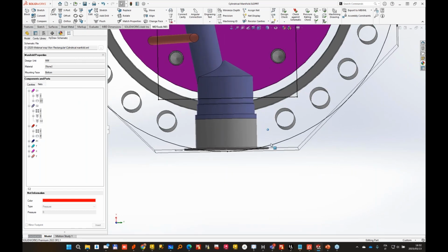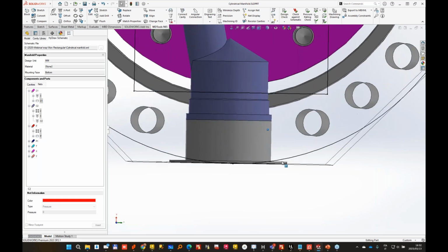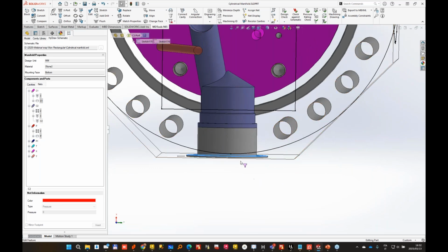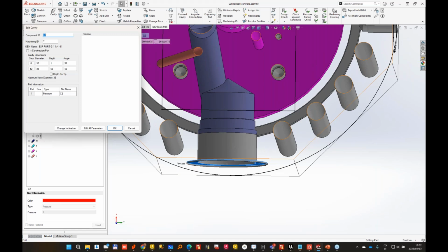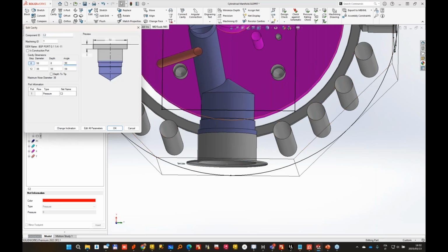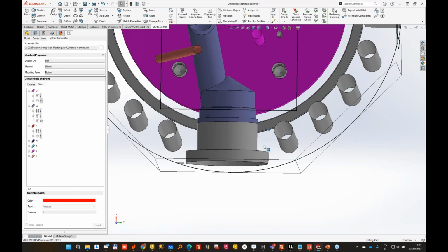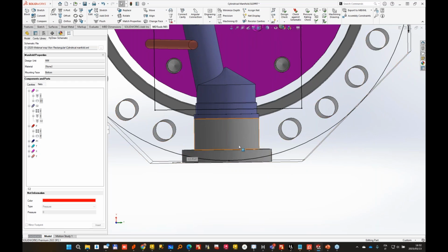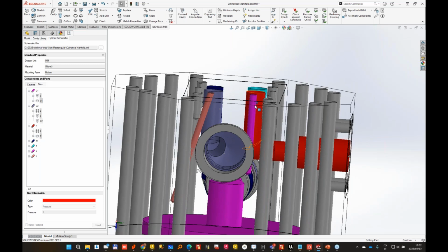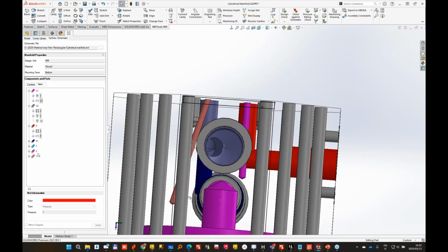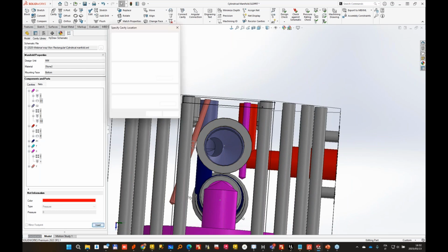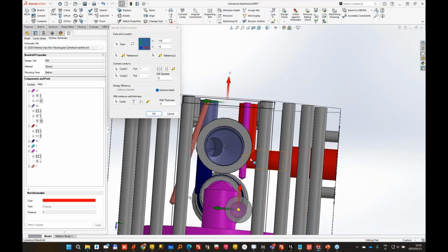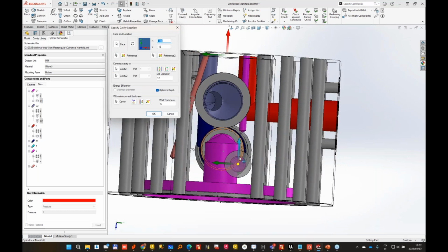Since, for the same statement I made earlier, I need to remove material, I need to sink this cavity a bit. So edit, and let me make it 8 millimeter deep, so that when I cut the external part to make the cylinder, I will see the full counterbore. This is the pilot X. So since I'm here, I will add also the pilot port here and connect it here. And the position can be referenced to another cavity. So dynamically, we can change the position with respect to another cavity and make it 65 by 20.